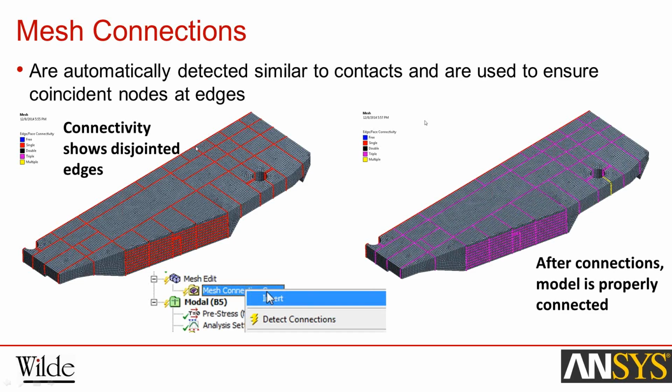By using the method highlighted here, we are able to take advantage of the parallel meshing features within Ansys Mechanical. What we mean by parallel meshing is that instead of each body being meshed sequentially, we can mesh many bodies at the same time so long as they have independent meshes. This parallel meshing feature is obviously not available with a multi-body part, as the mesh on each part is dependent upon the mesh with its mating part.